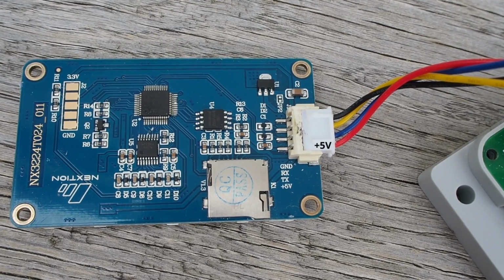Because all the Nextion display needs is 4 wires. It's 5 volts, ground, TX and RX. And I have those switches in here and they have a Sonoff Basic in them. And each Sonoff Basic has 5 volts, ground, TX and RX. So all I needed to do is to design the HMI layout, and I'll show you in a second how it's done. Then connect the display to the Sonoff Basic, add a few lines of code in the ESPHome that I use to control the Sonoff Basic, and then mount it.